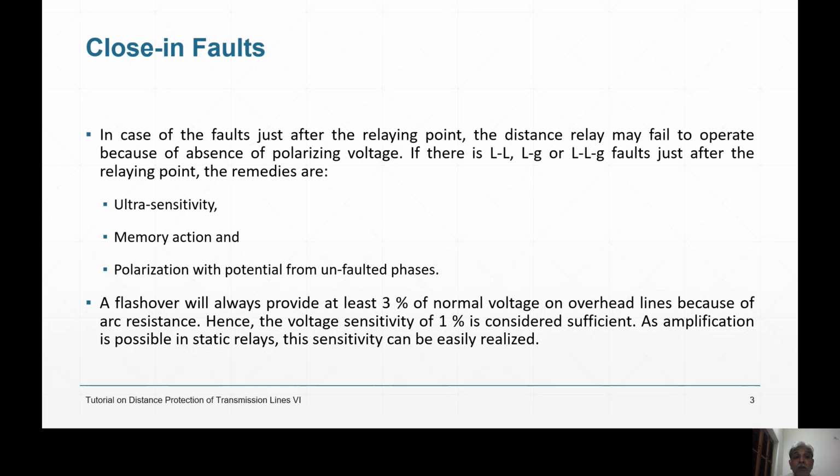Second thing, you cannot keep the fixed and moving contact like that only. Moving contact has to be literally stretched by a very tiny spiral spring, because otherwise it will operate by vibration. That is wrong, so you have to take care of that.